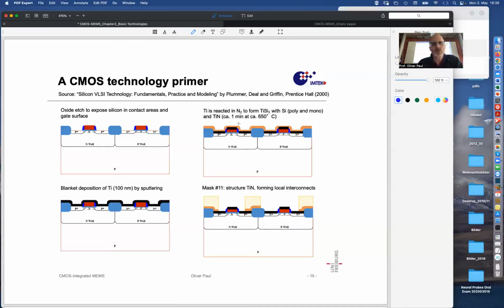Of course, it heats up the surface mostly, because heat comes in, energy is absorbed, and then energy needs time to diffuse also by conduction. And if this is heavy enough and short enough, the thermal energy remains at the surface, elevating the surface temperature. And then what can happen is that, first of all, the black thing, the titanium, reacts with the silicon into titanium silicide. So that's a compound of titanium and silicon.